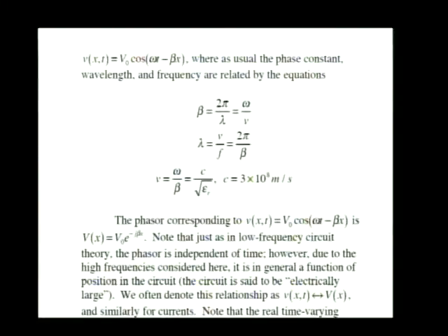For a 2-wire transmission line, I can identify an epsilon r. It's the dielectric constant of the medium that surrounds the 2-wire line. In a coaxial line, again, I can identify epsilon r. You've got the outer conductor, you've got the inner conductor, and between the two is some dielectric. And epsilon r to use in that equation, that's epsilon r of the dielectric.